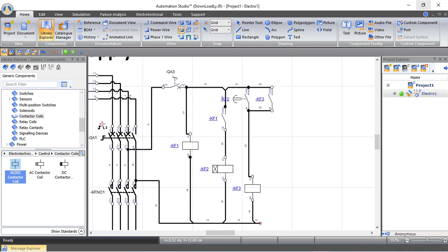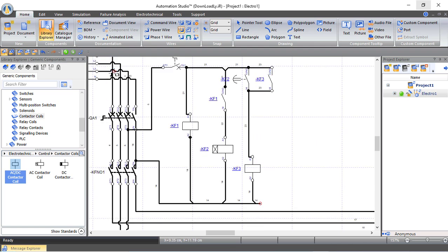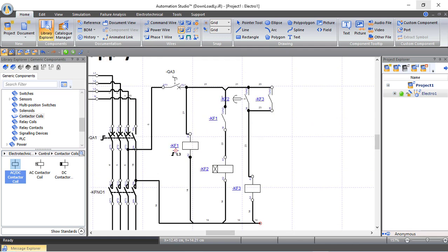Perfect. If this circuit breaker is closed and there is power in our main source, this relay will be working. So this will be closed and this timer will start counting. After a specific time, it will close this normally open contact, which will make the contactor close. And this latched contact will be working now. So the main power source will supply our load. Now let's see what if this relay stopped working, which means that this power source is not working.